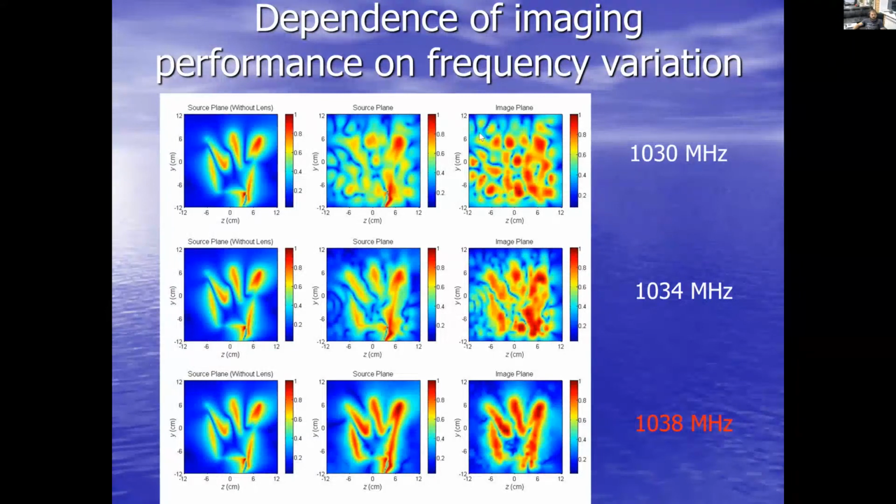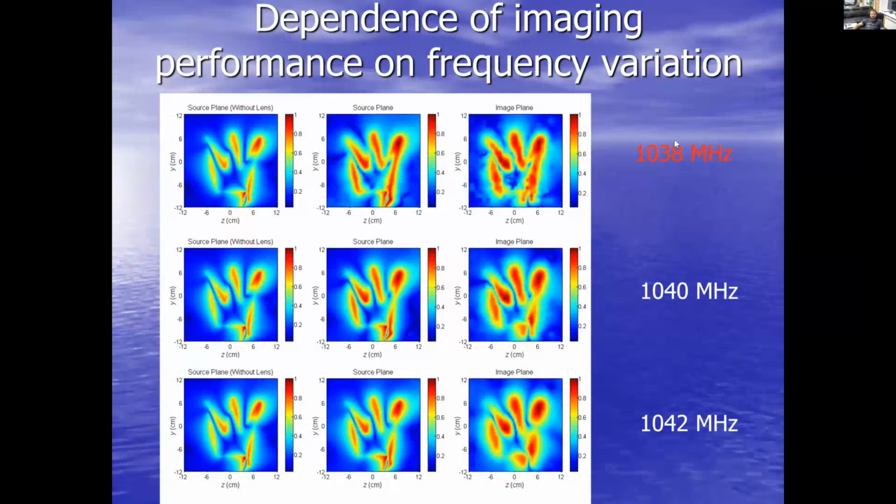There are some ripples and maximas. These are surface waves which are undesirable, but at lower frequencies below Fabry-Perot resonance, they do appear. And you shouldn't work below Fabry-Perot resonance at all. You should work right at Fabry-Perot resonance and a little bit higher. And at a little bit higher frequencies, there is no problem. You do have very nice images which reproduce everything.